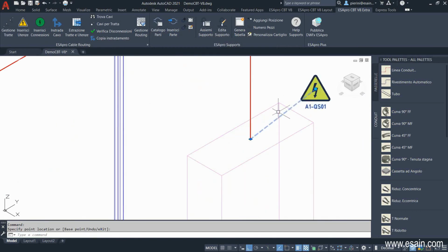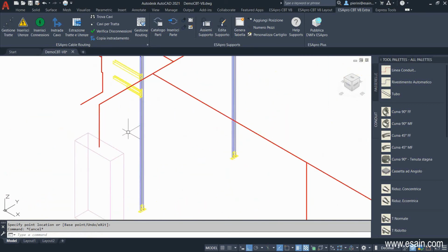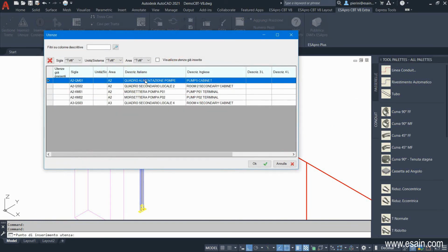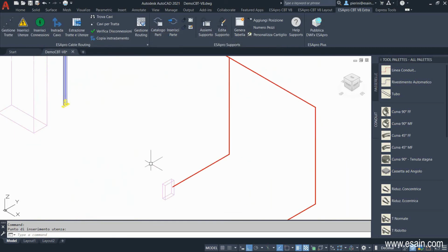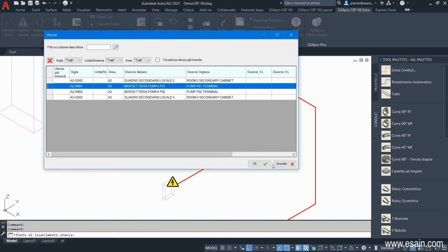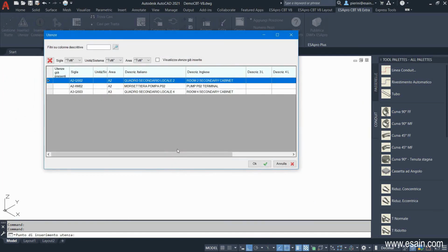These blocks can be stretched so that multiple users can be connected to a single axis. In the case of a series of panels, here we're going to insert the motors panel. We see that the list gets shorter as we go to add the users. So going forward, fewer and fewer users are shown. Let's go to add the 2 pumps. This is the P1 pump and the second terminal block, that of the pump P2.